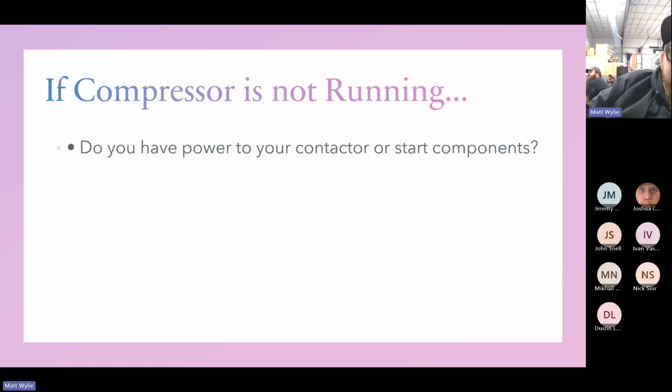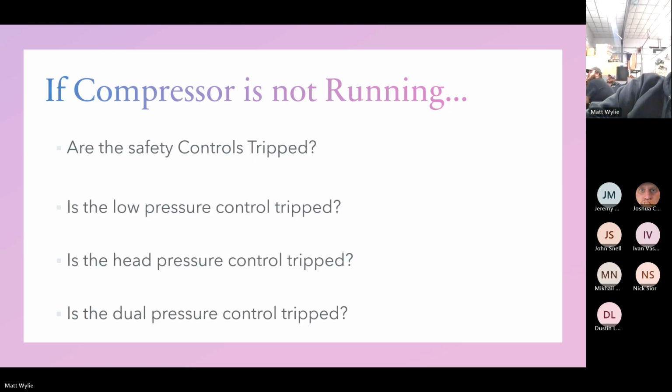So compressors. If the compressor's not running, do you have power to your contactor coil or starting components? Are any of the safety controls, like the low pressure, head pressure, or dual pressure controls, open? Check those.